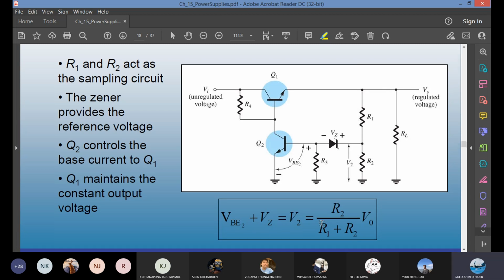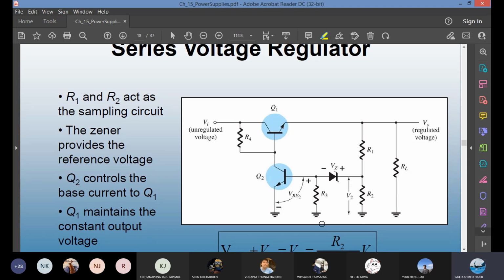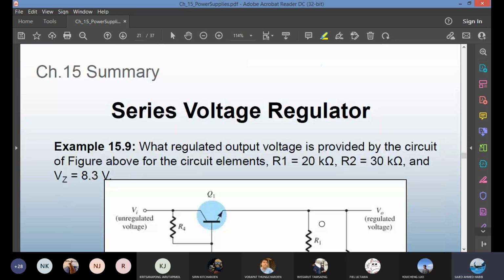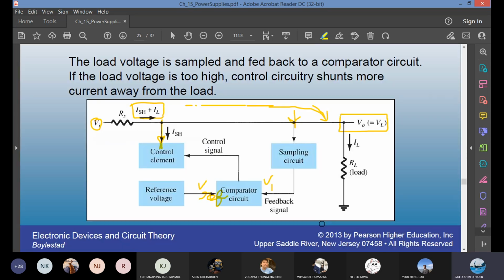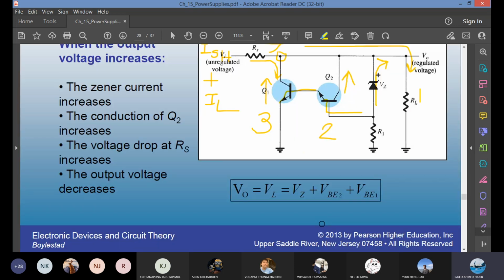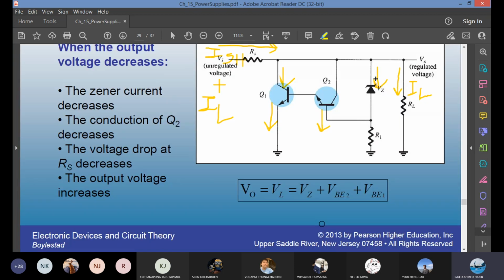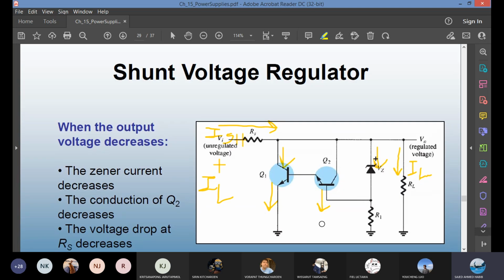So once you see a circuit, being able to recognize that is important. A shunt voltage regulator, we call this a discrete voltage regulator. Why discrete? You are picking some components maybe from the circuit lab or electronics lab. You can add all of them on a breadboard or solder them on a PCB. This is called a discrete voltage regulator, individual elements.